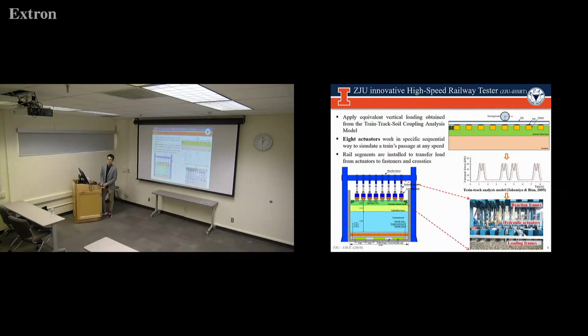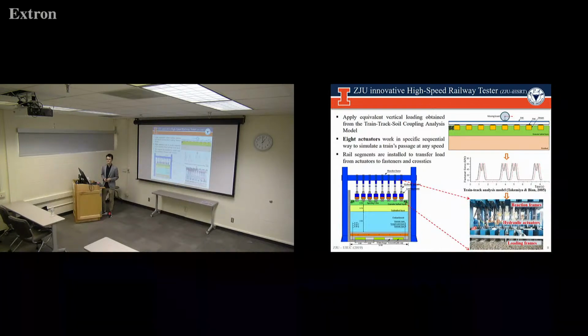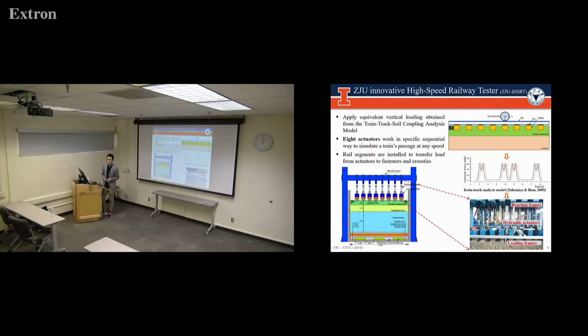Actually, in our RailTEC, back in 2010, there was a person, Brandon, who studied this. We have clearly shown that up to 3 times the typical static wheel load levels can be applied because of such dynamic impact load conditions.